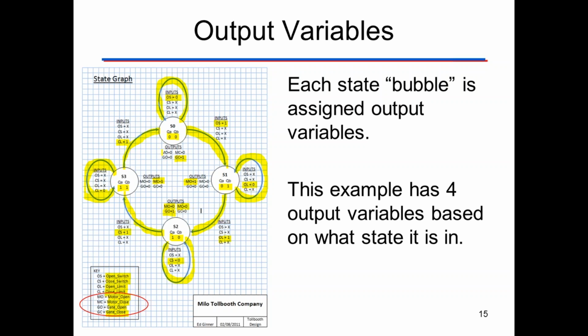And what we do is we turn the motor off, the closed motor's off. Our 2 state flip-flops go back to 0. Gate closed is equal to 1. And now we're sitting here waiting once again for the open switch to open.